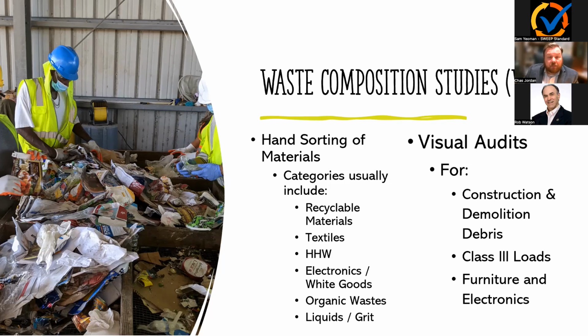Per ASTM, a sample should weigh no less than 150 pounds for an accurate data point. So in a community that's quite large, we may pick 30 to 40 samples that we would try to geographically or by the amount of generation from those sectors pick to strategically and statistically accurately meet as many different areas of that community as possible. But each sample, once we pull it from there, has to be a minimum of 150 pounds.